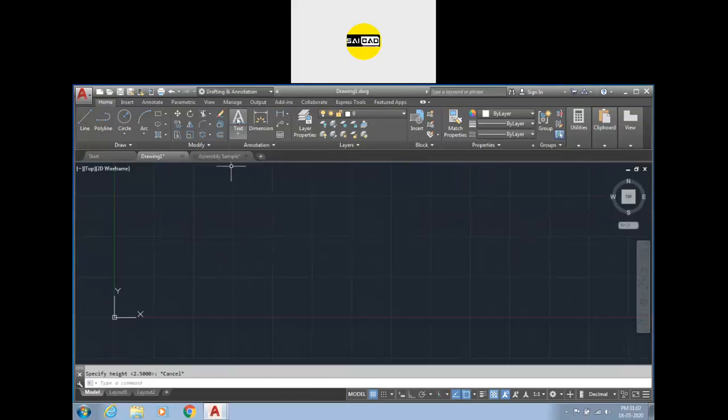Okay, so select the single line text and you have to specify the start point from where you want to create the text. I want this point. After that it will ask for height. You can simply just click for the height or you can define the height from command line. Next you have to specify the rotation angle. If you want the text to be at an angle, you can specify the value. I am not specifying, so just press enter, 0 will be selected.